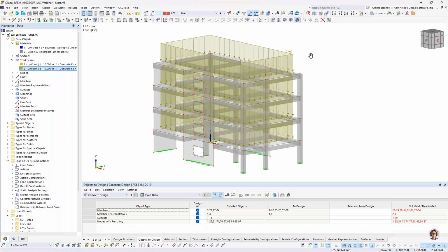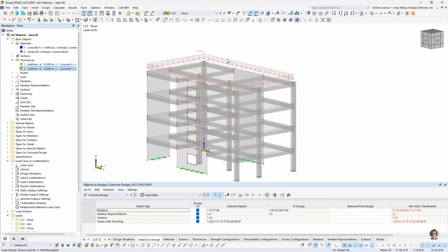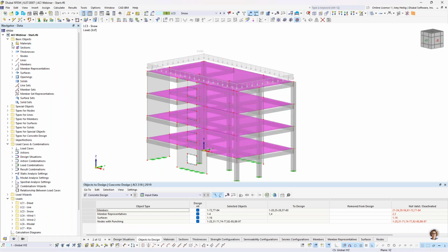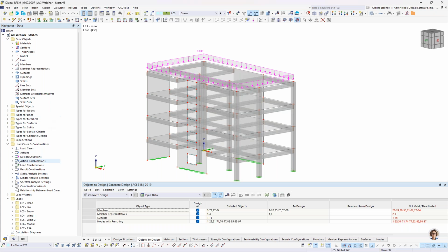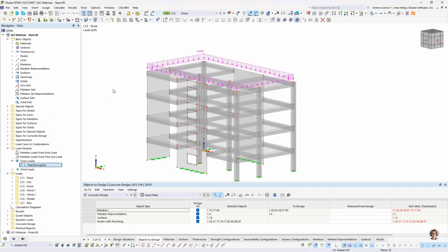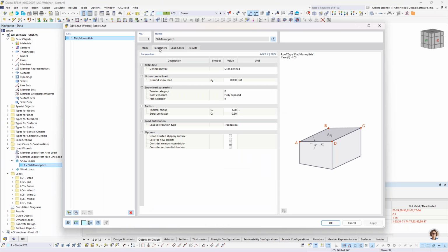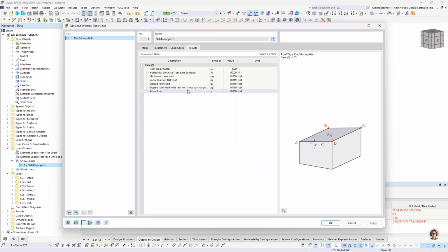We also have the live load case here, same concept. The magnitude for the surface load was increased to 100 pounds per square foot. Then we have our snow load here at our roof level. And for this, I took advantage of the load wizards that you'll find over here in our dialog box. And under the load wizards, if you remember, we set this to the ASCE 7 so that we can automatically generate the snow and wind loads. So if I go into this dialog box here, you'll notice that we just specified the geometry, we input the parameters specific to the ASCE 7, and ultimately the program is going to calculate these snow loads for us.